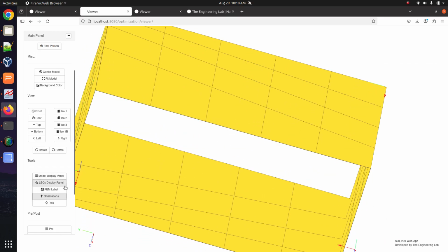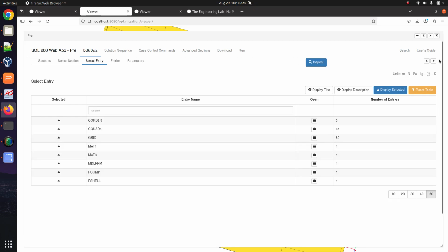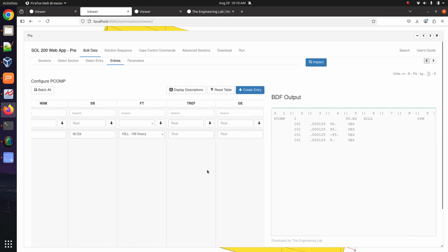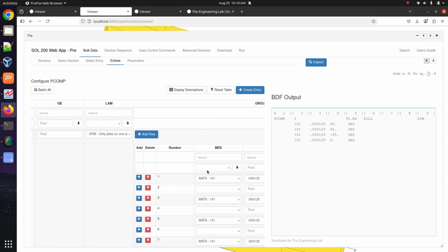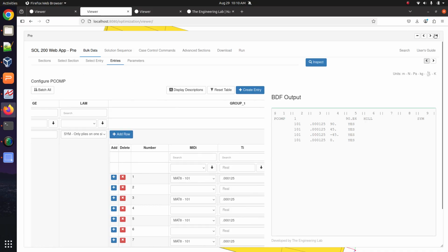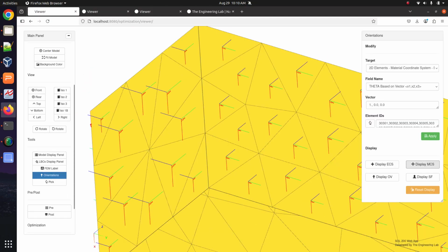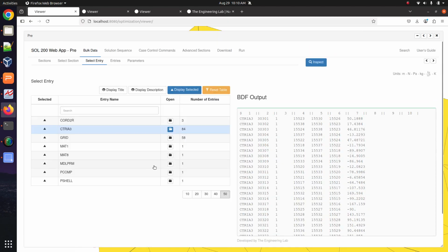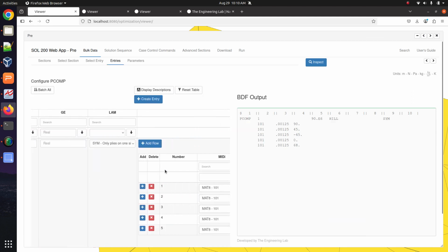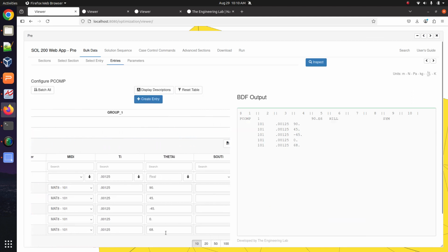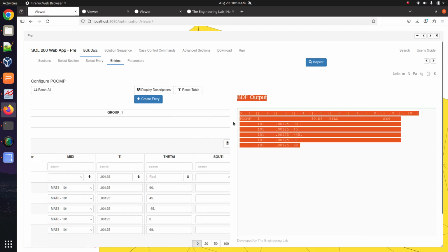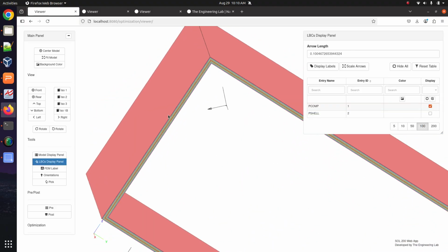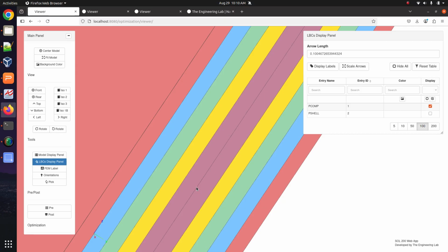And let me recap what we did in this video. So we went ahead and we modified the PCOMP entry. We added some additional layers, if you will. We then went ahead and saw a preview of this. I think it was in this one, actually. So we went ahead and built or updated the PCOMP entry. We added a new layer with 68 degrees. We saw how the PCOMP entry was written out. We saw a preview of this. So as we were building the laminate, we got to see what the layers look like.